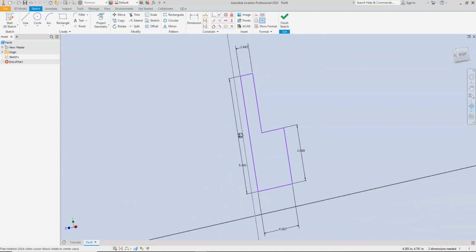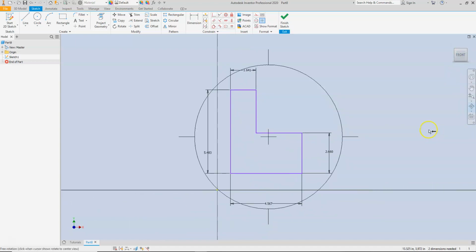If you get things spun around, remember that you can always come back up here and click on one of these cubes. Remember that I had the XY plane parallel to the front plane on my view cube. So I can pick the front view of my view cube, and we can turn that object around. If you get out of the correct orientation for your drawing, you can always work your way back. We'll go over the view cube a little more later. You do need to become familiar with moving things around, and that will come as second nature as we continue.